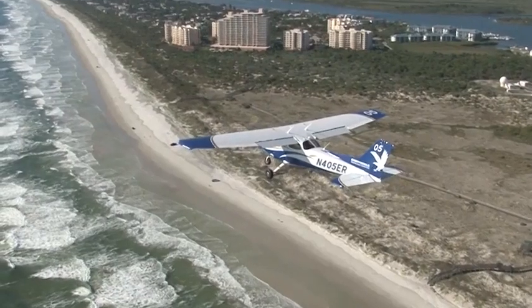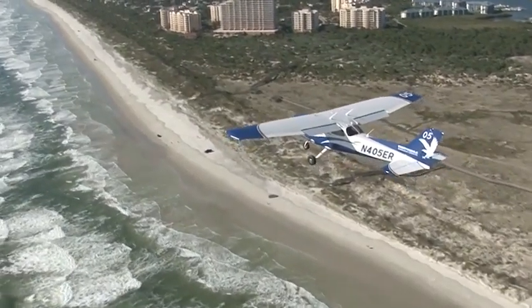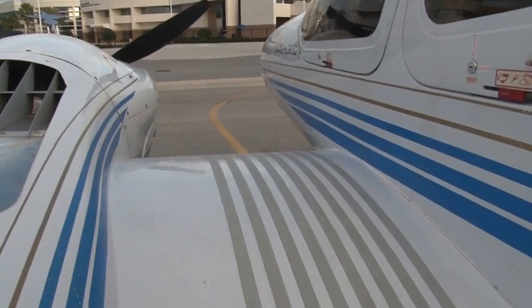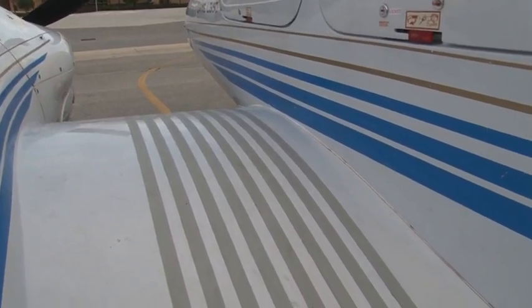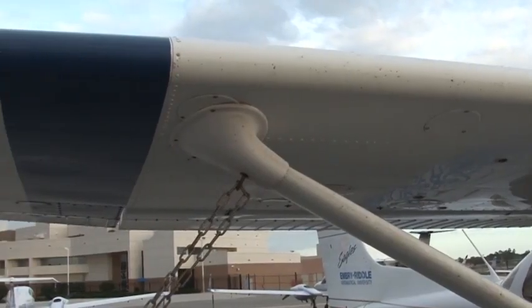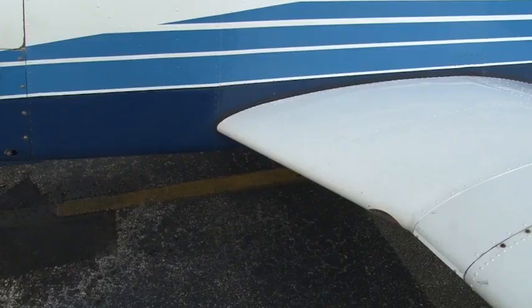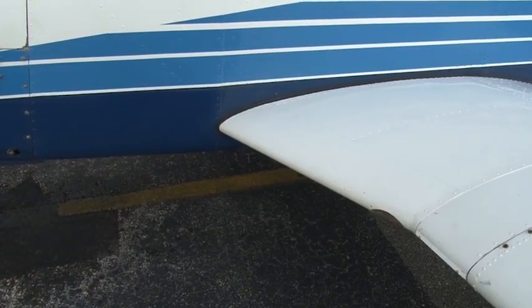Interference drag occurs in locations over the aircraft where different surfaces meet. For example, where the wings attach to the fuselage. Placing two objects close together will create up to 200% more drag than if each object were separate. To minimize this, manufacturers will place smaller, angled pieces at these locations.